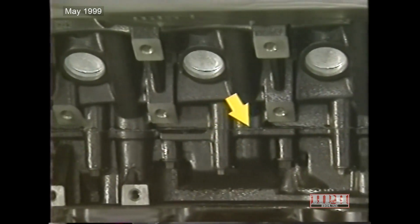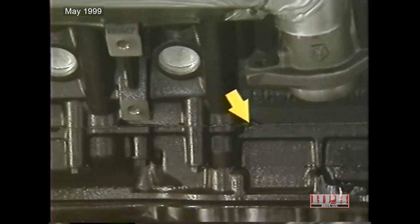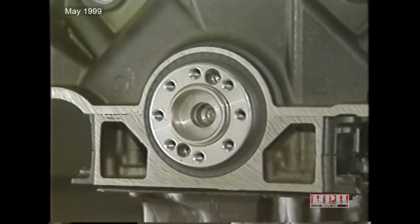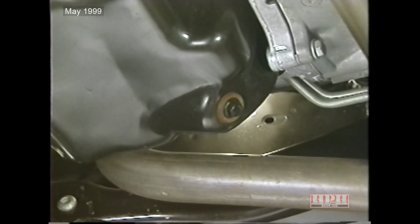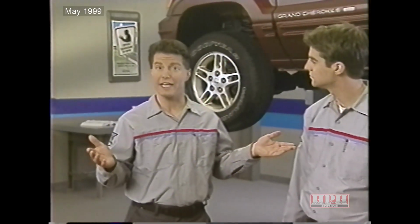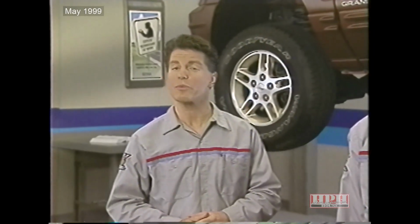On engines that are a bed plate design, check for oil between the bed plate and cylinder block mating surfaces. And check the rear oil seal area for evidence of leaks. Finally, check the seal around the oil pan and the drain plug. At this point, our diagnosis hasn't led us to any evidence of a leak. In a minute, I'll show you a dye test that we can perform to help pinpoint the leak source.